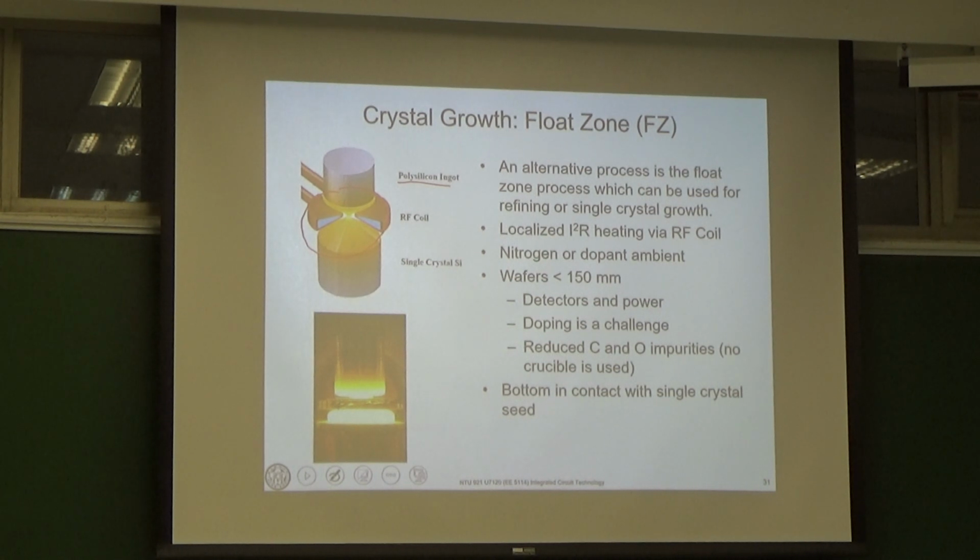Because of this segregation process, we can move defects into the melted silicon. As this coil continues to move upward, you can imagine that you draw all the impurities into this melted silicon. Once your coil moves upward, the region behind begins to solidify and turn into single crystal, and more pure silicon can be formed.